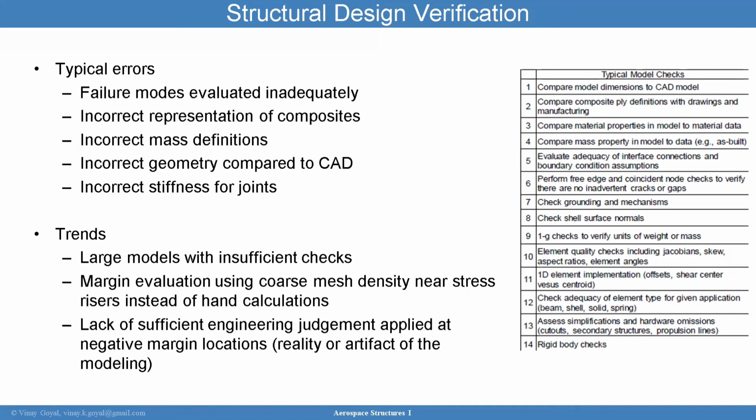So it's very important then to ensure your margin evaluation is done with the highest confidence approach. And it doesn't have to be the finite element model. Large models are being developed, but you want to make sure that if you develop a large model, you put the fine mesh in areas where it's needed and coarse mesh in areas where it doesn't matter.